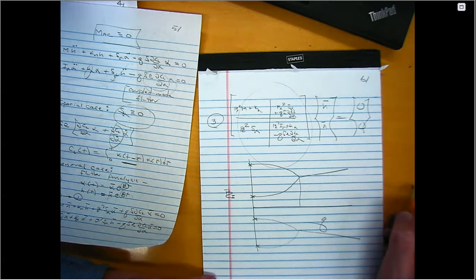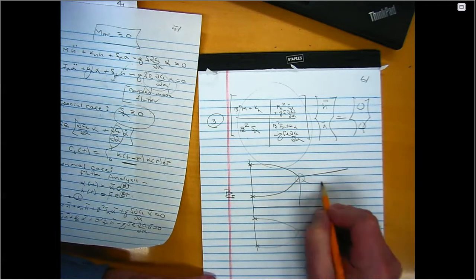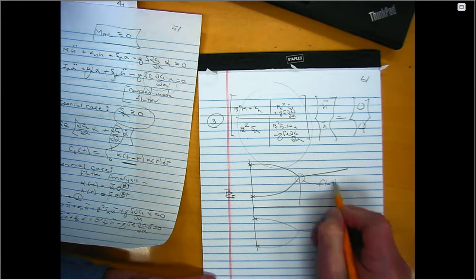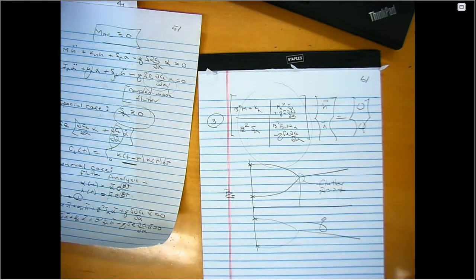One of the real parts will be positive, and one will be negative, and the one that's positive means I'm unstable. Right? So this is the flutter point in this simple model. And that's why coupled mode flutter is sometimes called merging frequency flutter or coalescing frequency flutter.